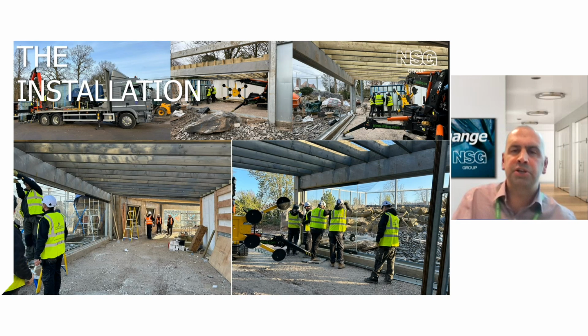So these images show the installation of the glass on site, which comprised 2 large screens and 2 smaller viewing windows in a cave-like walkthrough experience for the viewers, providing different angles and viewpoints of the snow leopard's habitat. Each screen opening is approximately 7.5 metres wide by 2.5 metres high, and these were split into 3 glass panels supported into deep rebated perimeter frames and structurally butt jointed on the vertical joints.